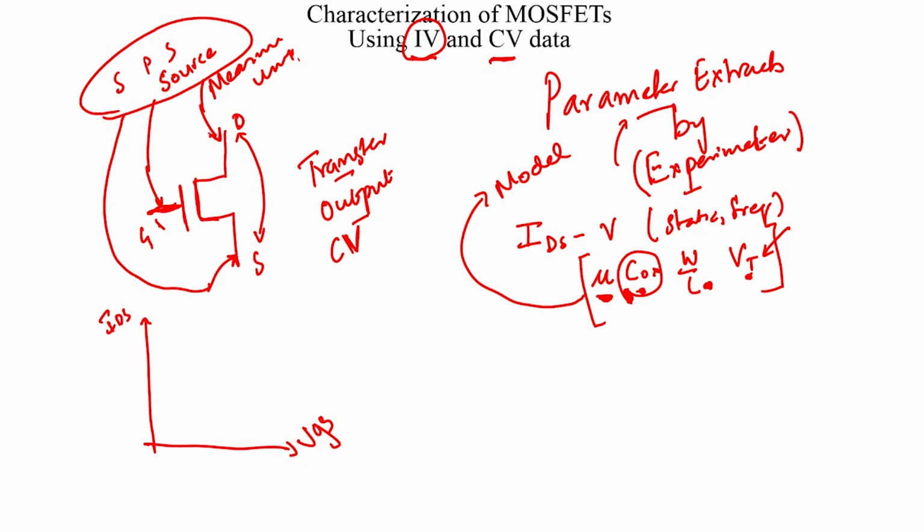And since we are going to be measuring very low currents in the MOSFET, you probably want to be using triaxial cables for current measurement. Okay. So, after making this connection, you want to be varying the gate to source voltage after setting a certain drain to source voltage, and we will end up with a characteristic that looks like this.